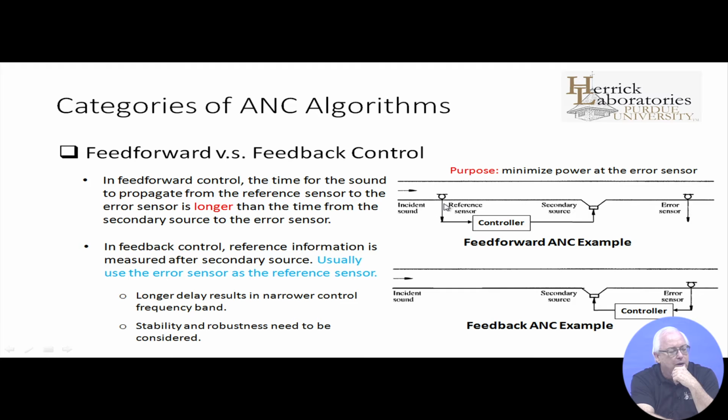Whereas the idea of feed-forward control is more or less straightforward, that you sense the offending signal before it gets to the point where you want to cancel it, and that gives you enough time to process that signal, feed it to the secondary source, and get it to the point where you want to achieve the cancellation in time, as it were.